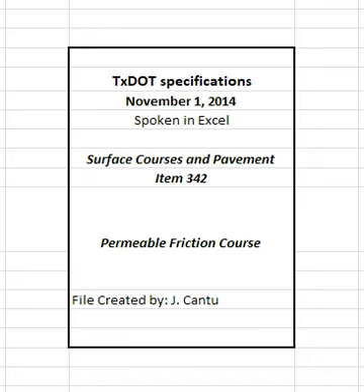The engineer may suspend paving operations if the contractor cannot successfully modify the paving process to eliminate recurring severe thermal segregation. Provide the engineer with electronic copies of all daily data files that can be used with the thermal imaging system software to generate temperature profile plots upon completion of the project or as requested by the engineer.